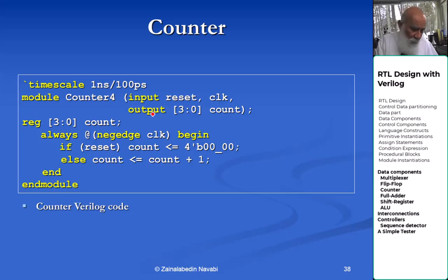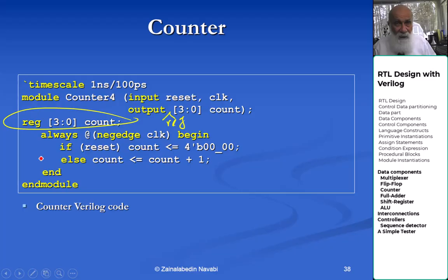I could of course also include reg over here, and if not, then this is also one way of doing it. Why do I declare count as reg? Because my intention is to give it an assignment, or put it on the left hand side, inside an always statement.